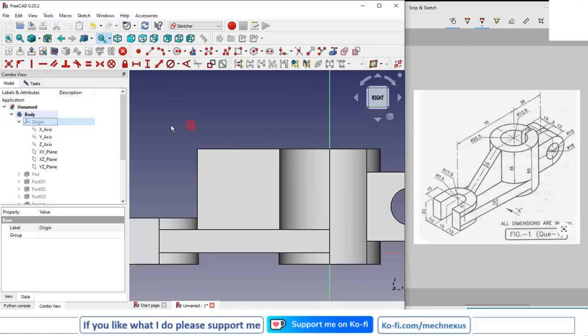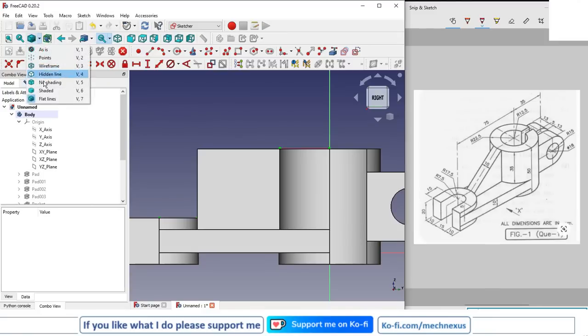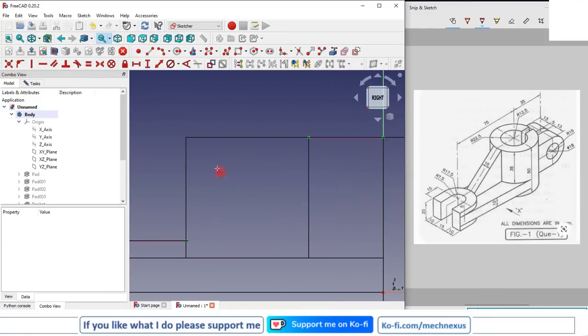Now I will project the geometry, this point and this one, and I will switch to the wireframe. Now I will create a triangle. I will also project this, and I close my profile.